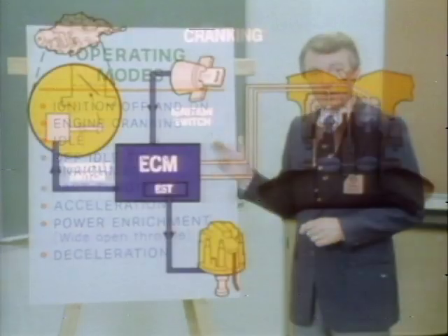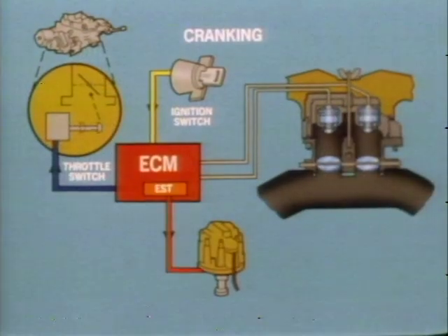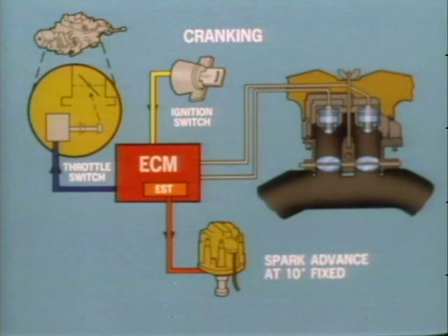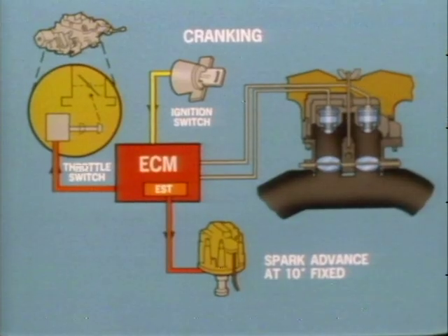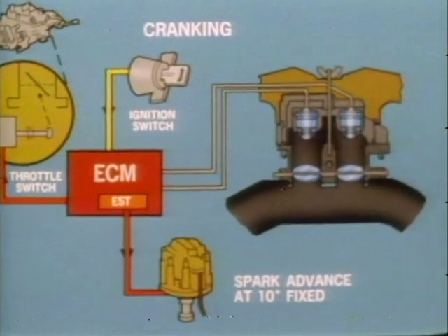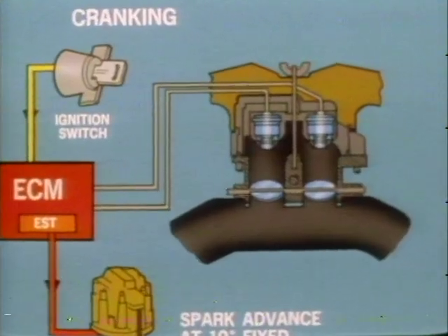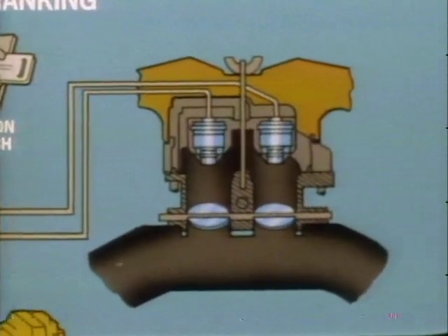Cranking. When the engine begins cranking, the EST system maintains spark advance at 10 degrees, while the ISC actuator holds the throttle partially open to facilitate starting. When cranking begins, the ECM issues prime fuel pulses to provide an initial fuel charge for starting.